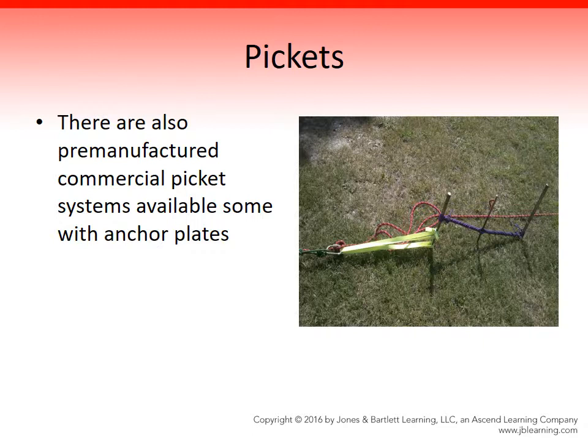Tension the lashing by twisting them with a stick 4 to 6 turns and drive the stick into the ground to secure it. Connect the main line by clipping it to the front picket.